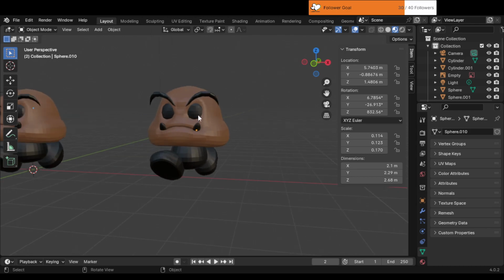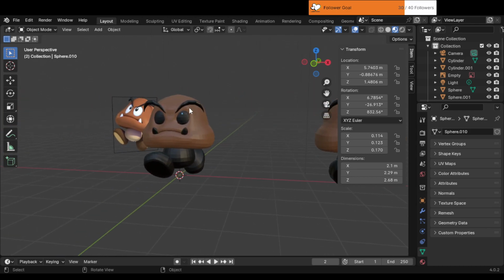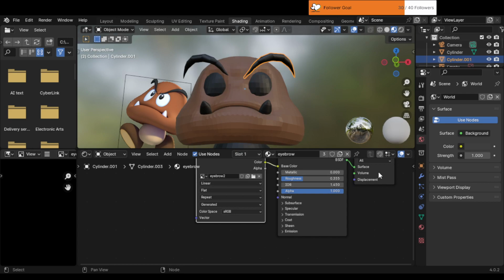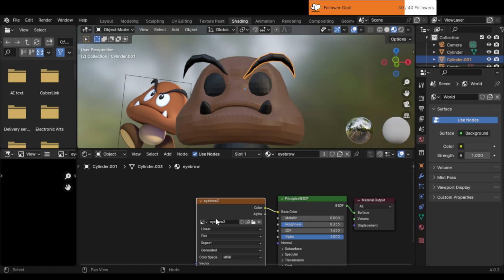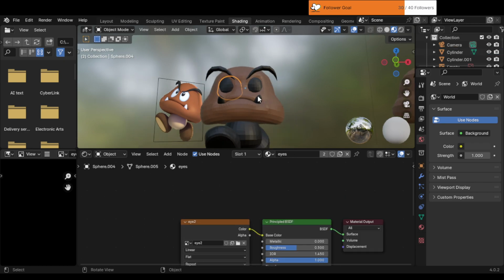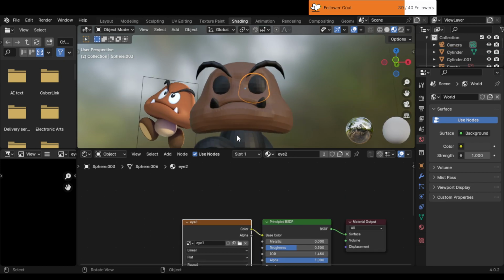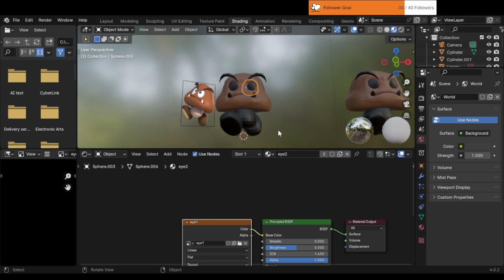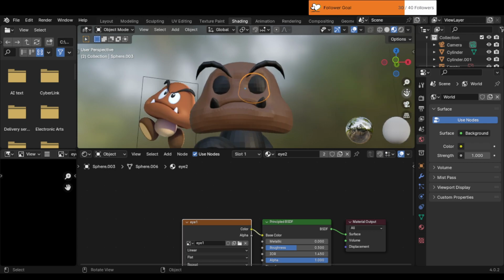Troubleshooting and solutions. 1. Check mesh integrity. Inspect meshes. Ensure the joined items form a clean manifold mesh. Look for any intersecting faces, holes, or other non-manifold geometry. Separate items. Consider separating joined items into individual meshes and see if the operations work better on each separate mesh. 2. Simplify the geometry. Reduce complexity. Simplify the geometry of your model or joined items to improve the operations performance.